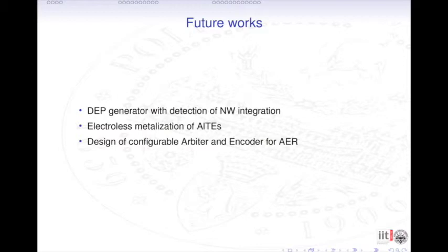And finally, as already mentioned, a configurable arbiter and encoder can improve the performance of an address event representation bus for transmitting the signal from a large number of readout circuits.